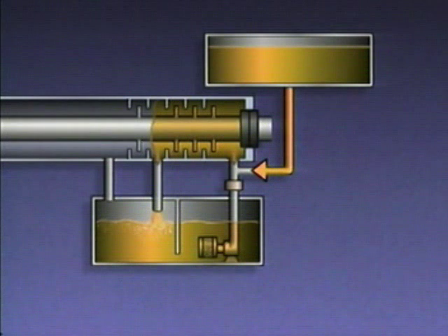The head tank is used to supply oil to the seal if the pump fails. The check valve keeps the oil from the head tank from flowing down into the oil pump and forces it to flow through the seal. The head tank contains enough oil to allow the compressor to be shut down without a gas leak if the seal oil pump fails. The next components we'll look at are bearings.